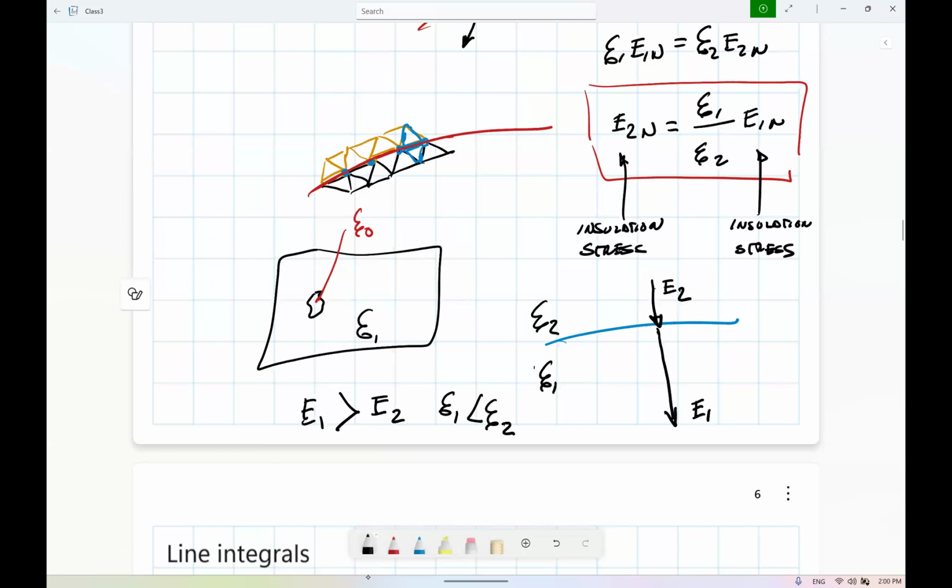No silly questions. Okay. So that means if designed properly, there can be some kind of transformer based on this. But there is a difference in the electric field, which means that you need to put thicker insulation than what you need. But it can also tell you that it doesn't matter how thick you put it, the stress keeps on growing, depending on the value of your permittivities. All transformer manufacturers know that sometimes if you put more insulation, you will only create a larger stress.